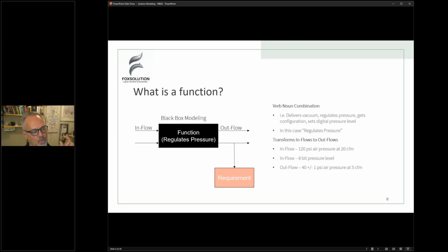It might be one thing if we're using pressure and we don't care if it's plus or minus 5, we could get that off the shelf. But if we have a harm associated with rupturing the eye globe, we might need much better control of that vacuum source. If that's the case, we need to think about this not as an individual component, but as a system that's going to require closed loop control.